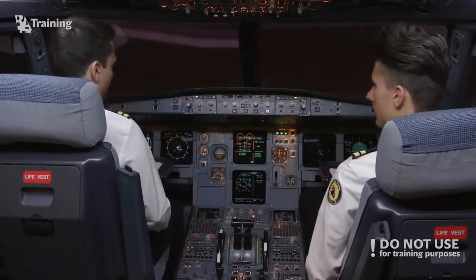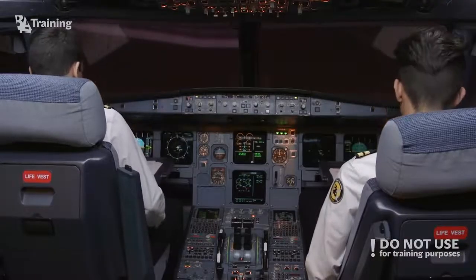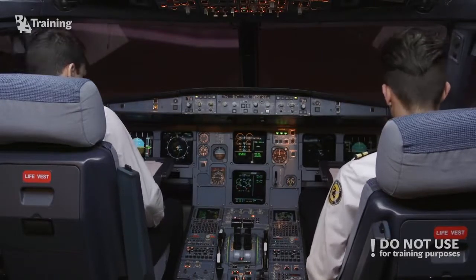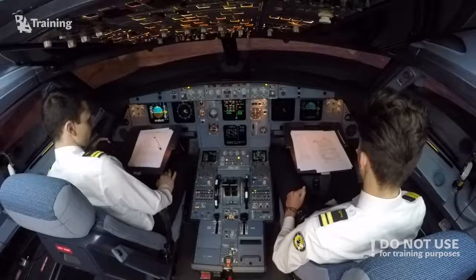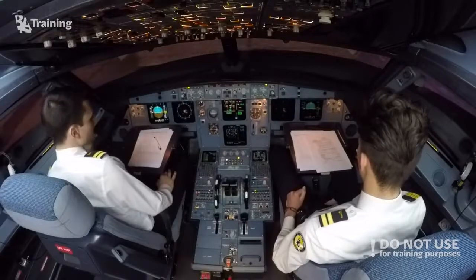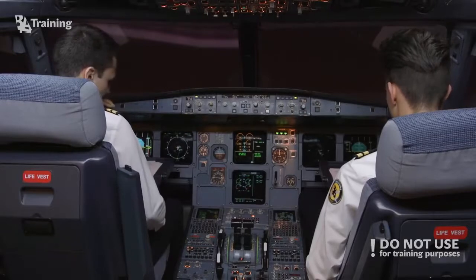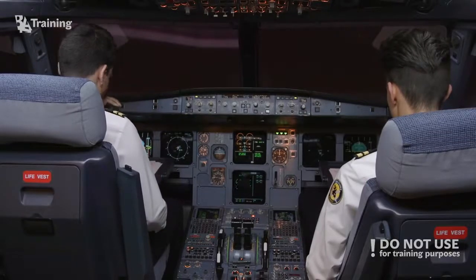Okay, let's see with the ground handling. Copy. Ground from cockpit. Go ahead. Are you guys ready down there? Doors and hatches are closed and steering pin is inserted. We are ready. Okay, stand by. We're going to call for push, and be advised we'll be starting engines number 2, then number 1.